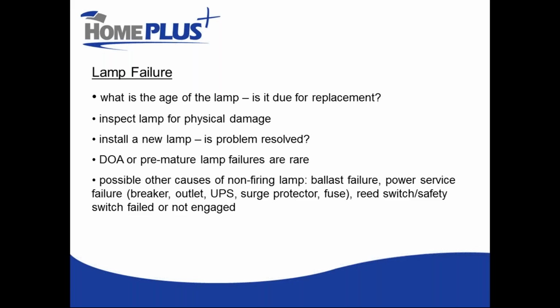And at 1 ppm, that's about 10 minutes or a little bit more than 10 minutes. And effectively, because we might have shortcutting, we might have to have a vessel that provides for a contact that's even much more than 10 minutes on average, because we have to think about the worst case scenario.